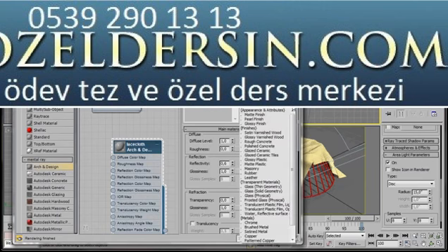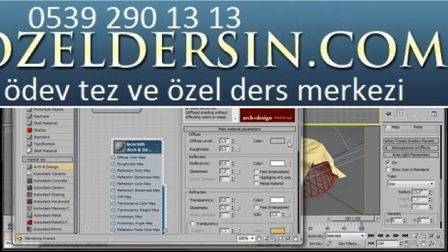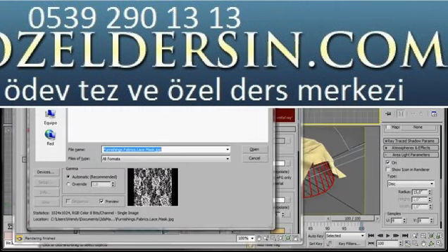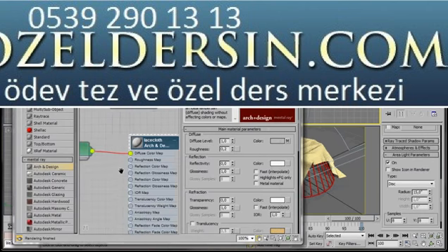Let's go over to templates. And we're going to select another matte finish template. Click on the small icon beside the diffuse color slot and double click on bitmap. I have the two maps in my Scenes Assets folder, but you can get these maps from your program files. Just go to 3D Studio Max, Maps, Arch Matte, which means arch material, and then click on Furnishing Fabrics Lace. There we are. Now we've attached our first map.